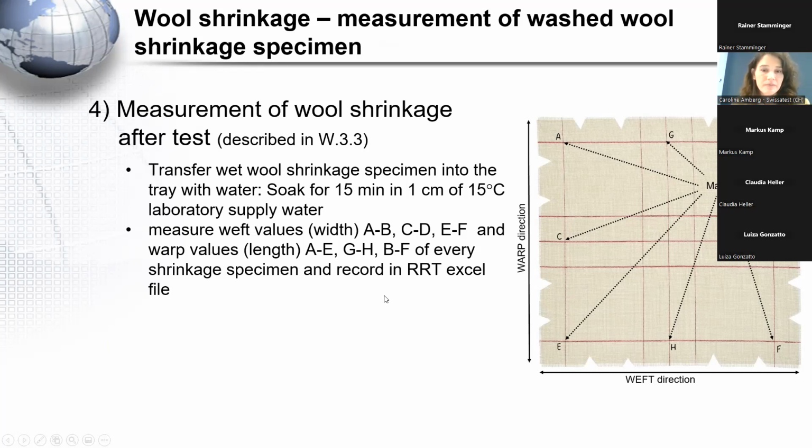Okay. And do you have any kind of recommendation for the operator, like a distance from the tray, something like that, room illumination? Because measuring this type of specimen submersion in the water is a little bit tricky. Yeah. Well, there is a recommendation that the water amount should be 1 centimeter high. And if you have a transparent ruler, it's anyway not super accurate, I have to say.